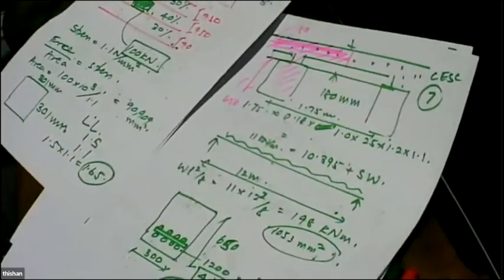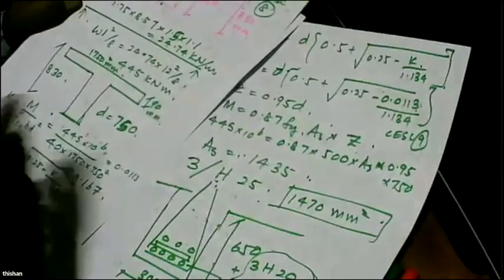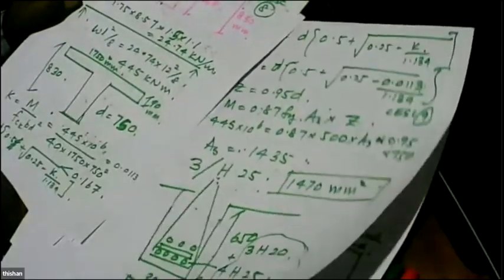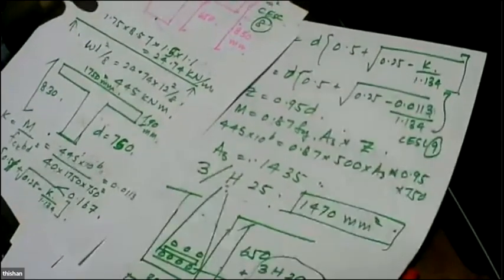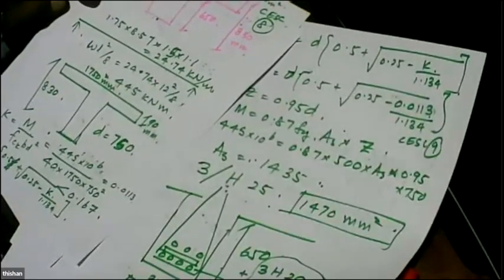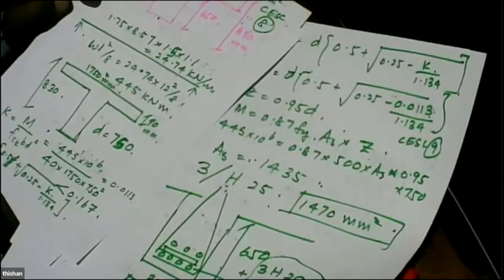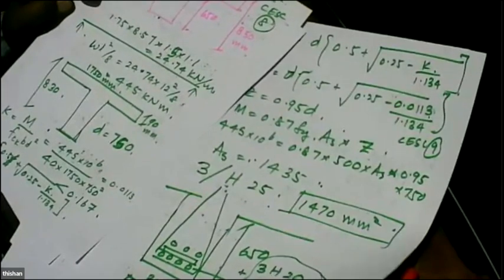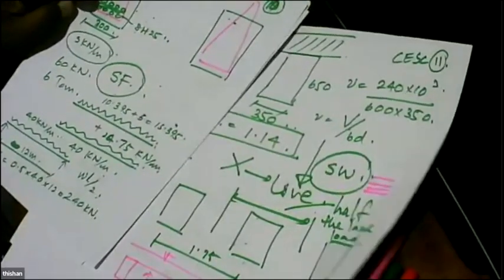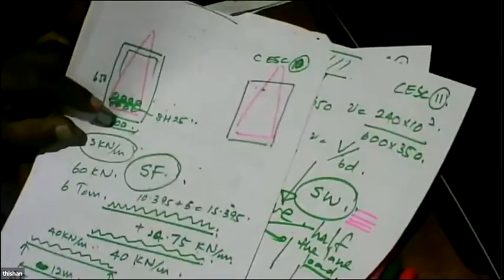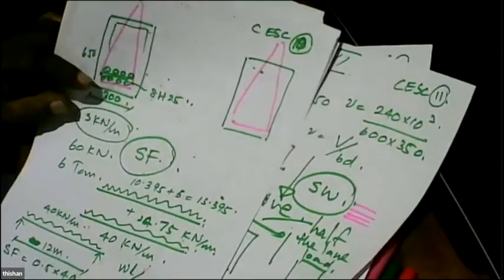And then we looked at the beam, and we said the beam is again loaded in 2 stages. For each stage, we calculate the reinforcement separately and add it up. And then I showed you the shear is not very critical, and we can make the assumption that shear is going to be taken only by the precast section.